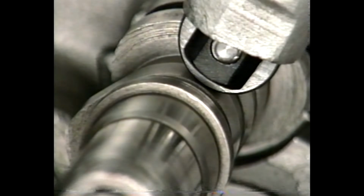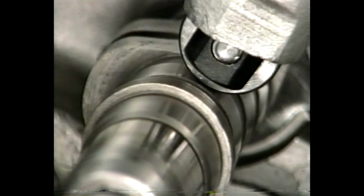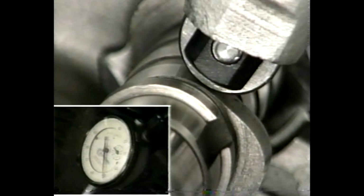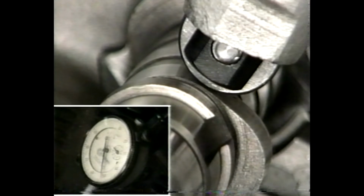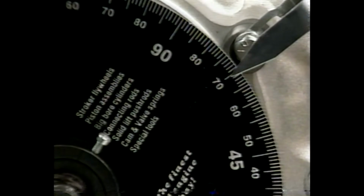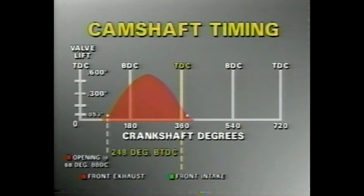We keep rotating the crankshaft until our lifter has traveled far enough up the opening ramp to be 53 thousandths of an inch off the base circle of our camshaft. Holding the crankshaft in this position, we record the reading on our degree wheel, which is 68 degrees before bottom dead center, or 248 degrees before top dead center.